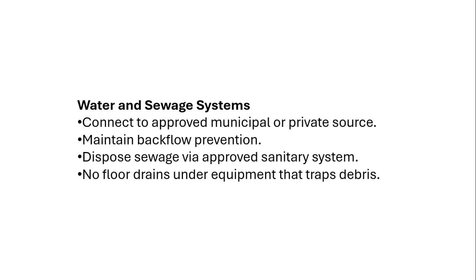Water and sewer systems. So they should be connected to approved municipal or private sources. They should maintain backflow prevention. We should be disposing of sewage via approved sanitary systems. No floor drains under equipment that trap debris should exist either.